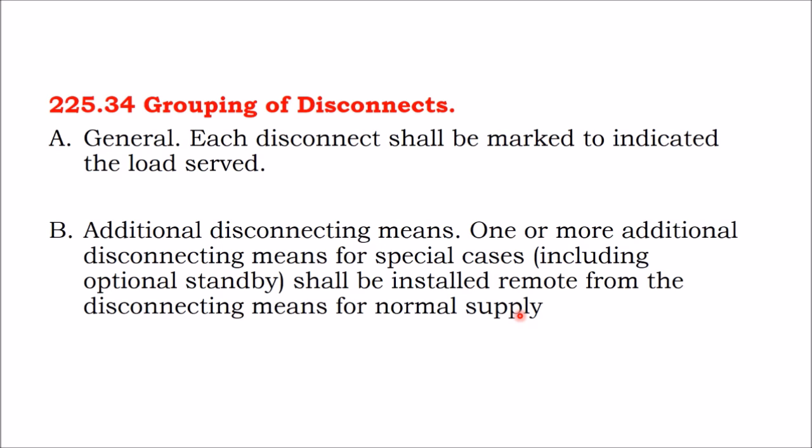Well, you need a standby switch. Well, what if the standby switch is powering grandma's respirator and it's there for an emergency rather than just a backup? And so the fire department turns off grandma's respirator when they're trying to save her. So we need to give some more thought to emergency disconnect locations.